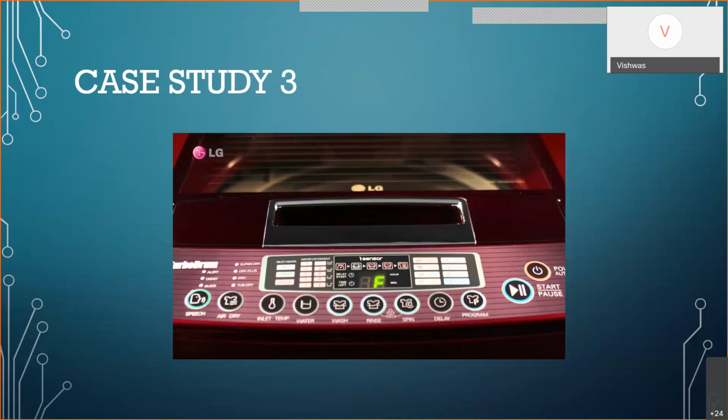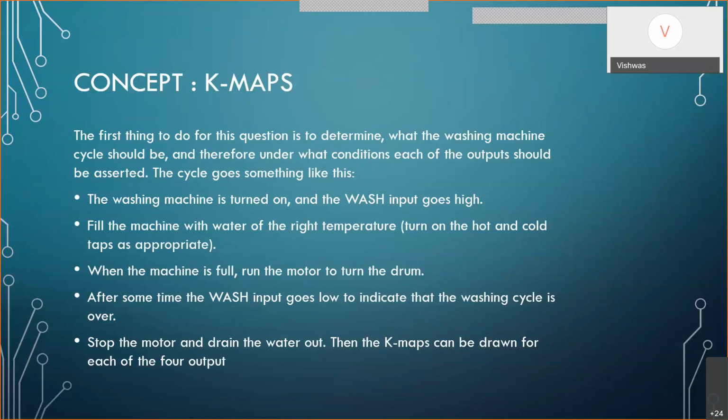So there are multiple ways to control. The main control variable for the motor will be the RPM. RPM will be controlled through PWM, the pulse width modulation. So you'll be having multiple control variables, and how will you realize that using a simple digital electronic circuit? We'll just list down the process of what needs to be done.